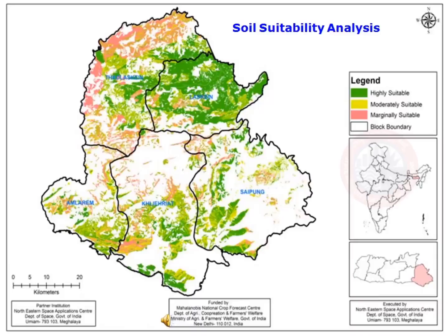Soil suitability analysis. Based on the different soil properties on a GIS map, it is possible to decide the type of crop or plantation to be grown or to be taken up. Also, we have to consider rainfall condition, topography, terrain conditions, climatic conditions, availability of irrigation facility, groundwater table condition, period of crop or plantation, etc., with vector layers overlaid to arrive at the result of suitability analysis.